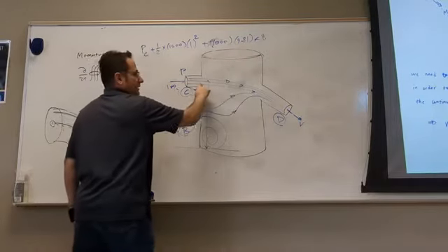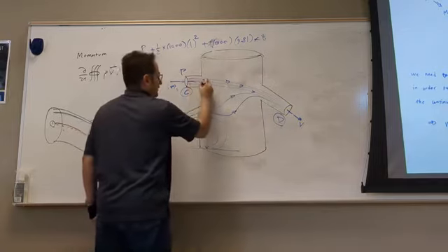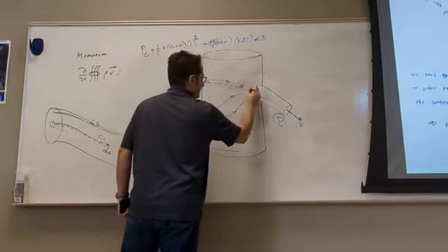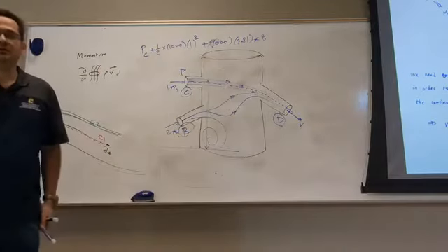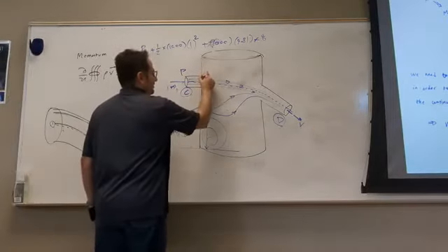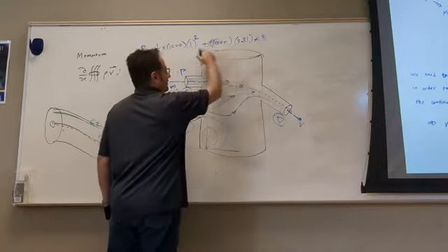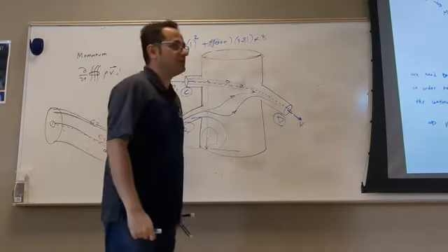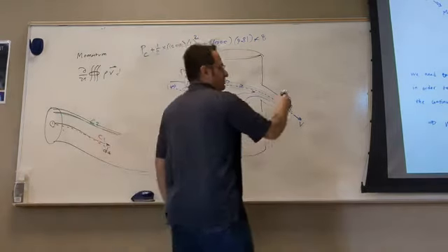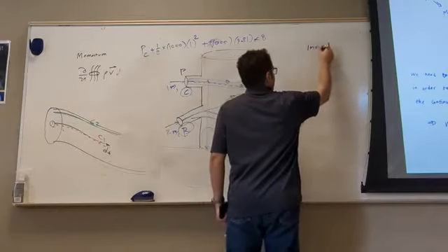Now this sum is constant over this streamline. Do you see that? It's constant over this streamline. But if I take this streamline right here, can I write this equation? No. Not as long as I don't have an irrotational assumption. So my only assumption right now is inviscid.